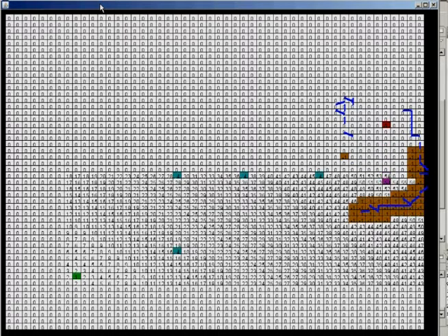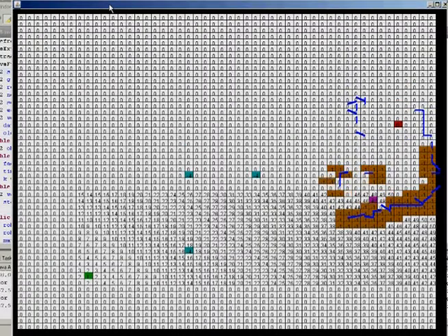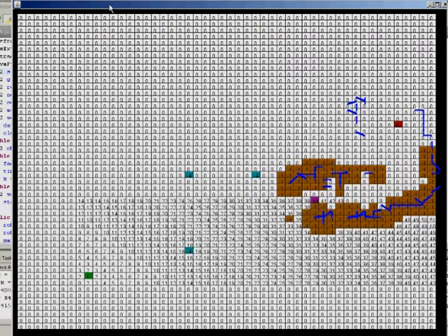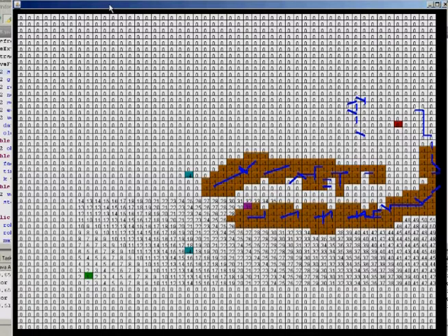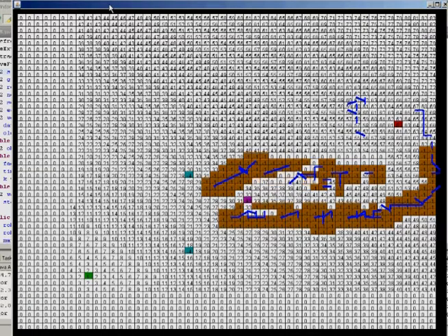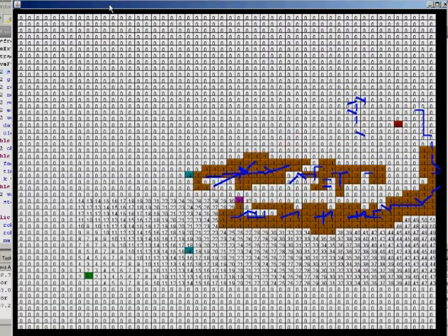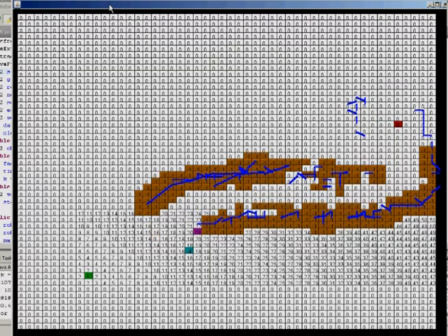I'm going to talk about avoiding obstacles. Our robot has the capability of avoiding obstacles. When it sees an obstacle, as you can see in one of the videos showing the computer vision, it treats it the same as a wall, so it won't go into the wall. We also have a configuration space, so whenever a wall is occupying a grid cell, we also mark the 4 grid cells connecting to that cell as occupied. With those two functions, we were able to detect walls and obstacles, and avoid obstacles while we are heading to the next waypoint or going back to the home position.